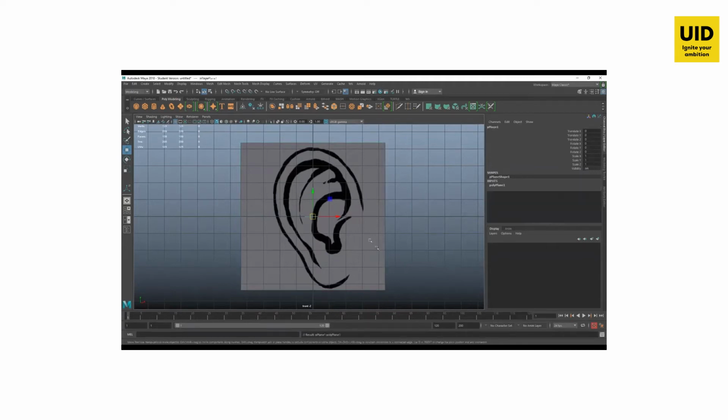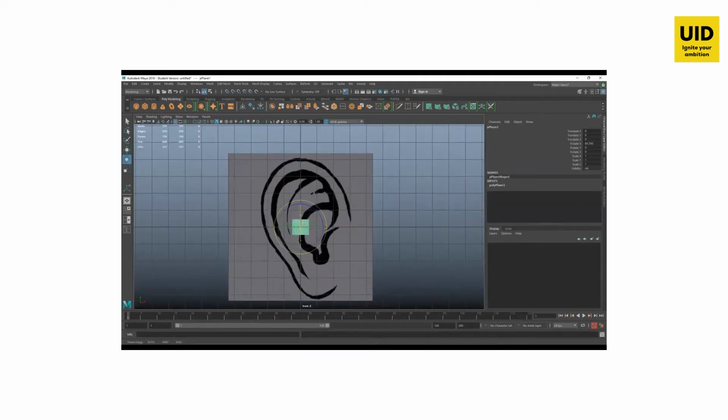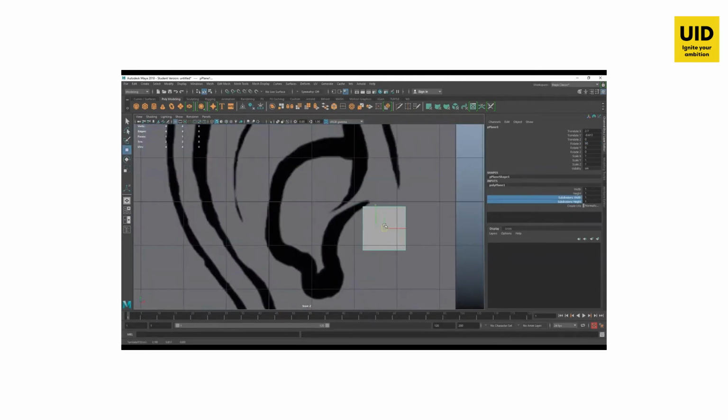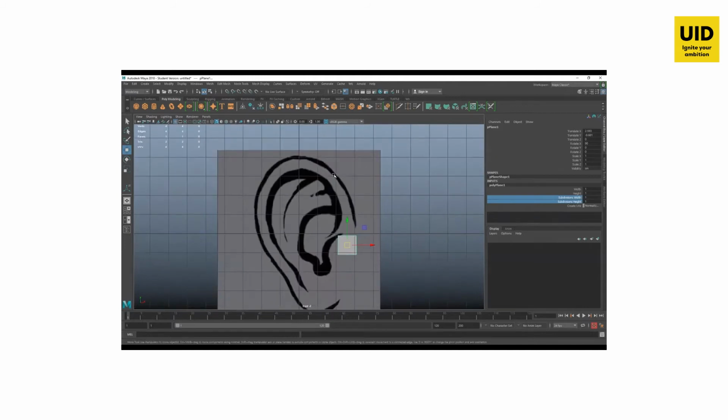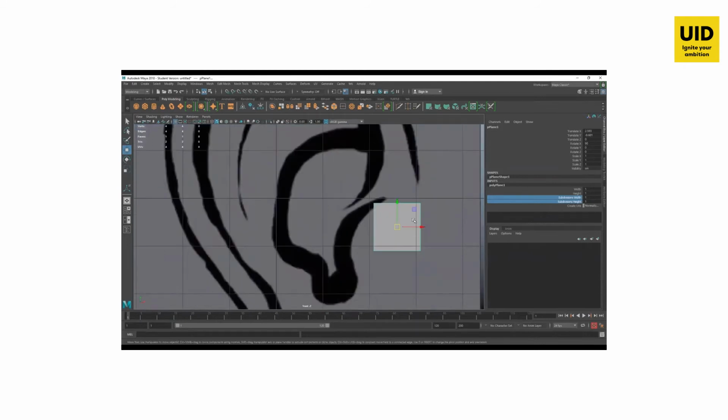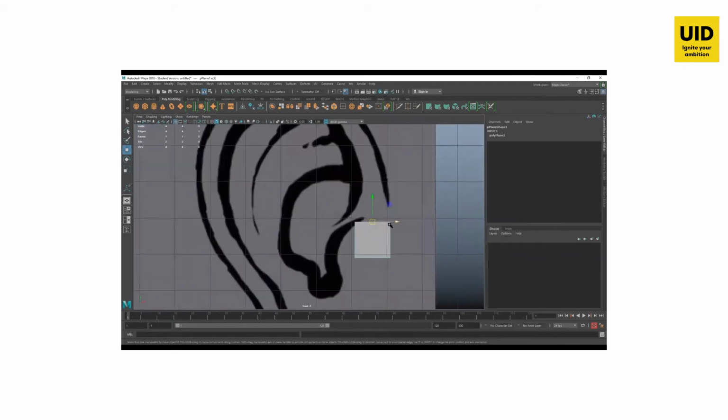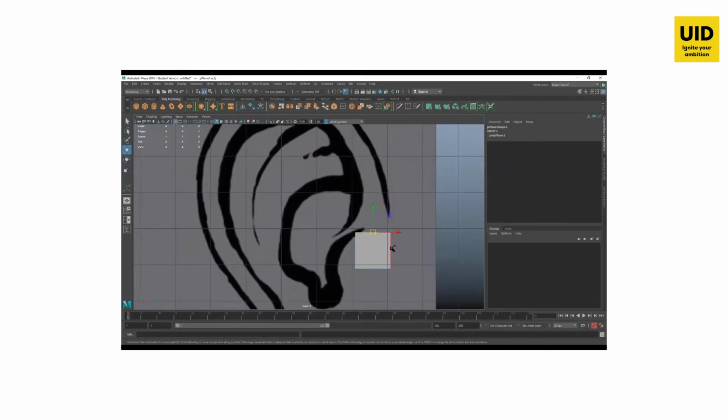So I'll start with a plane. We'll take a plane, 90, keep it over here. Polyplane, and I'll reduce all my subdivisions. I don't need them. Just a plane, a simple polygon. Okay, let's start from here. We'll just trace the outer boundary edge. I'll go to my edge and start my tracing. Control E, extrude.